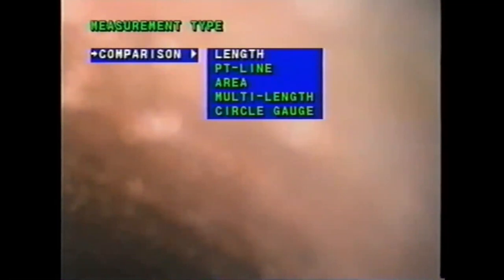So when you do system loss analysis, when you're looking at the energy loss in the system, does it take into account the pumping losses from all that scale? This is probably not pumped. Say this water is supplied to the top drum, and in most, well, it depends. Some boilers are called forced circulation, mostly utility boilers. These industrial boilers, it's just water falls by natural circulation. Because if you've got water on one side of the tube and water and steam on the other side, this side is less dense because the steam bubbles take up a fair amount of volume. So you got more weight on this side than on this side, and it forces a natural circulation through the system.